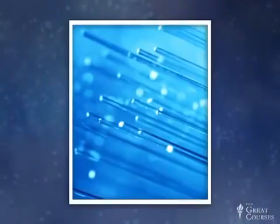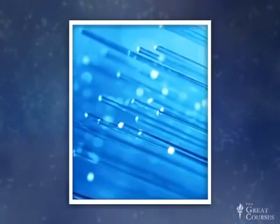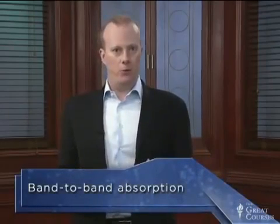There's another really crucial aspect to the ways in which optical fibers have been designed and constructed, and that relates to loss. Clearly, to ensure that our signals go as long as possible without losing information, without losing power, we're required to make this glass as transparent as possible. There's a variety of mechanisms by which light can be absorbed in any medium. A first one is what we call band-to-band absorption.